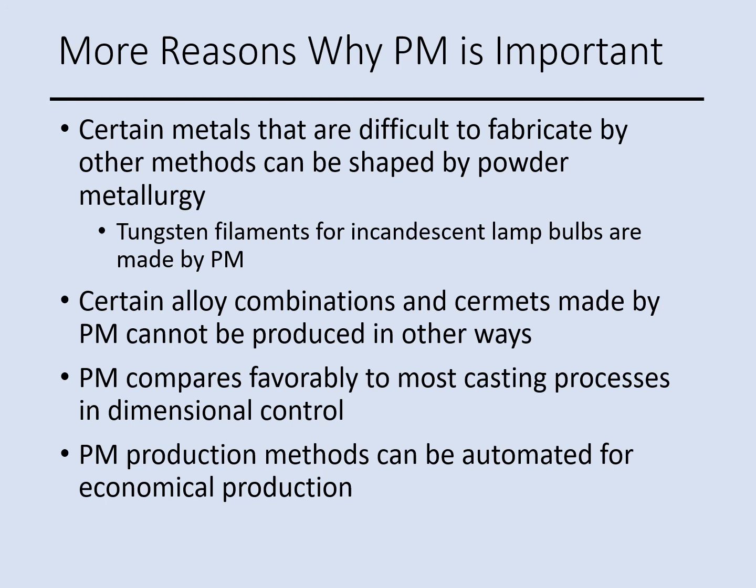For example, in PM we have a punch and die. So here is the die, and this is the punch. We can add one type of metal powder in a certain ratio at the bottom, and we add another type over there, and we can add a different powder on top of the previous one.